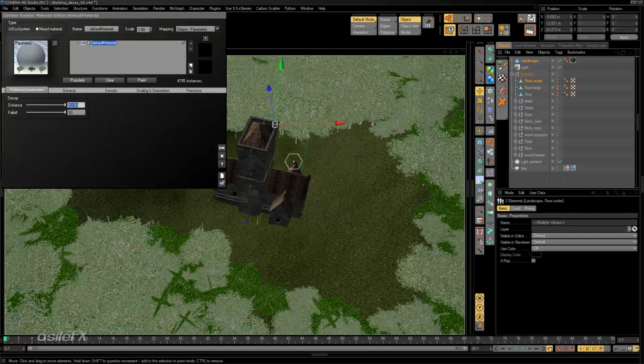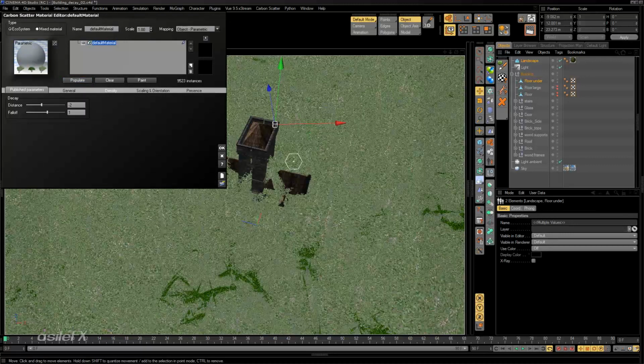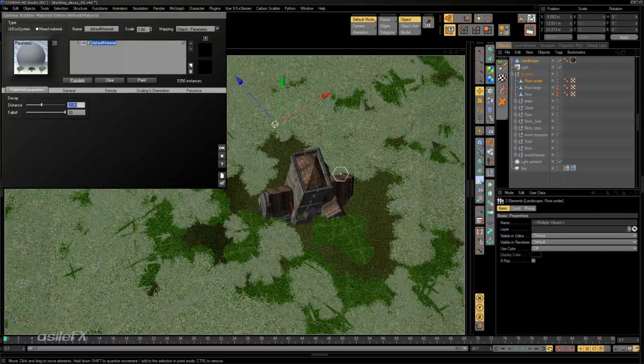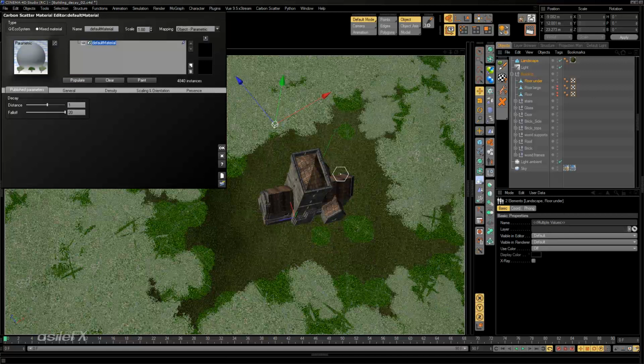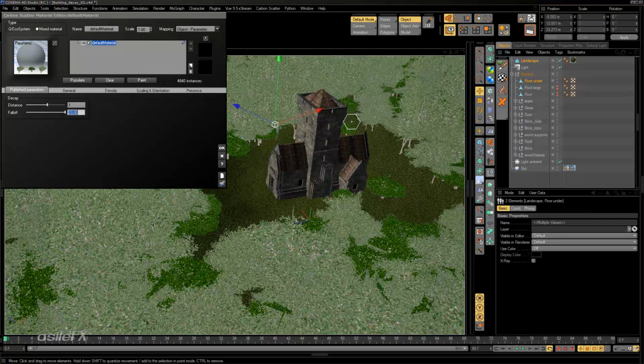Now, if the distance is too high, obviously if we start with a distance of 20, that's going to be the full range, which is going to give us a very harsh cutoff. The falloff amount, I don't even think would matter at this point, because we've gone beyond the 19 meters. Also, since we are in the negatives for the distance, that can modify and change the way that shows up too. So we want to be at least 0 to 1, if it's as close as I currently have the object. So it gives us a really nice transition range.